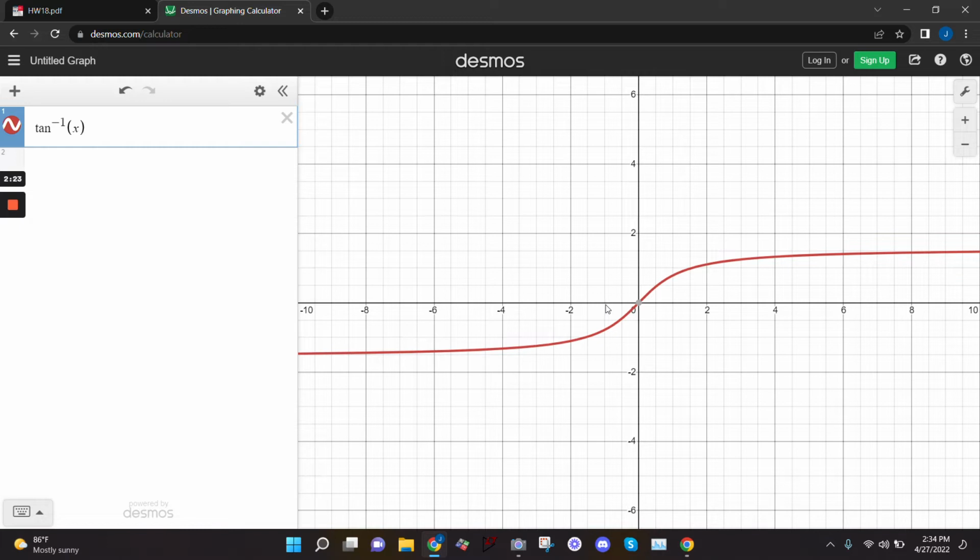And when you do a resistor, you plug in 0 over something because there's no imaginary part. The imaginary part is 0. So if you're trying to find the phasor representation of an inductor, you're going to get 90 degrees every time for the phase. For a capacitor, negative 90 degrees every time. And for a resistor, 0 every time.